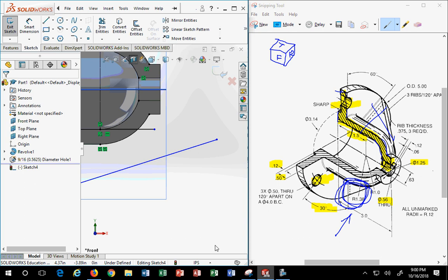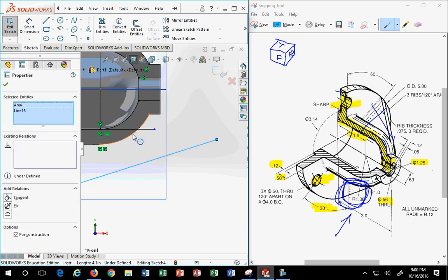When you have a high-end toy, like SolidWorks, when you're using those high-end CAD toys, use them! Don't revert to trying to do something by hand when you can make the software do it for you. So in this case, I'm going to hold my control key down, pick my line, pick my arc, and pick tangent. Let it do the work. Okay?